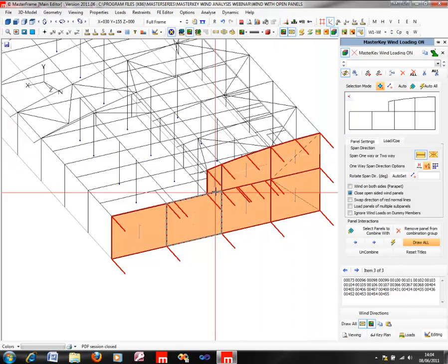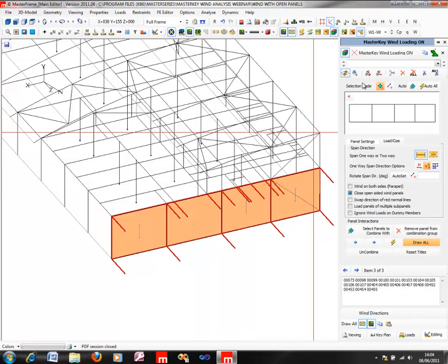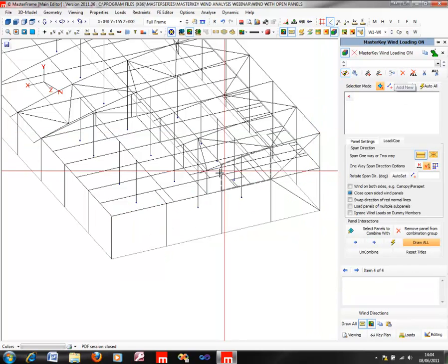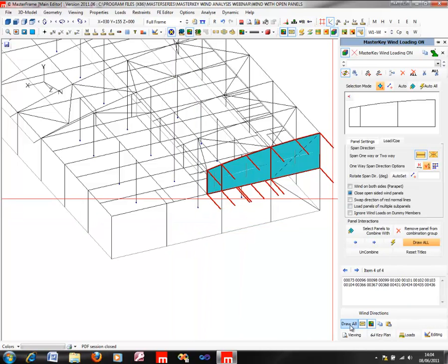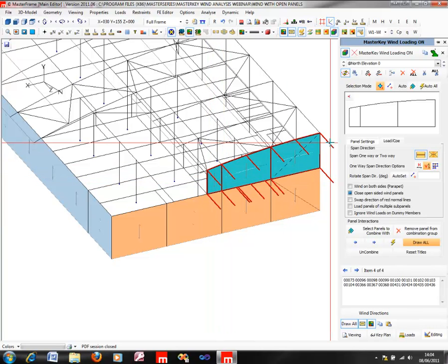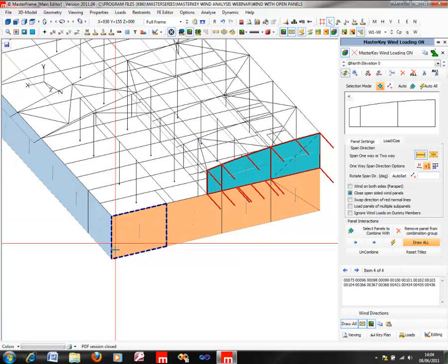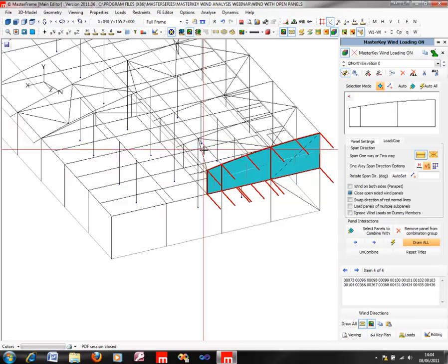So to that end, we would recommend that you would split up these types of panels so that they are horizontally banded, so you can have that facility of having a different leading wind edge. So we've now got two panels. If I can draw all the panels down here that we're doing so far, we can see this is a separate panel from this, meaning that this can have a different leading wind edge and really start its own zoning from this location, as opposed to taking the zoning starting from the overall panel location. So that's something to bear in mind also.